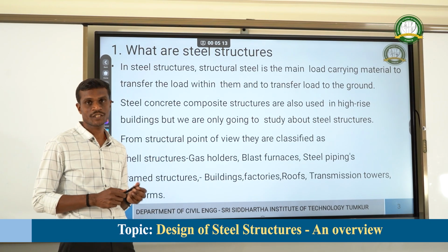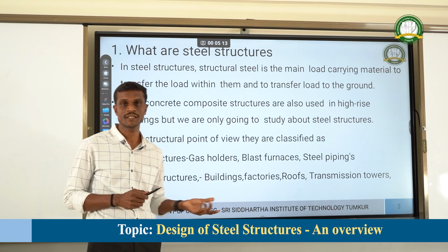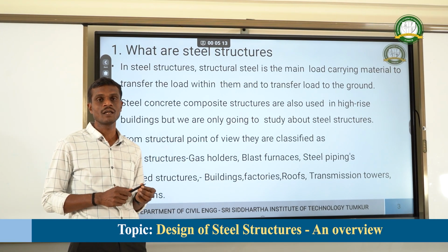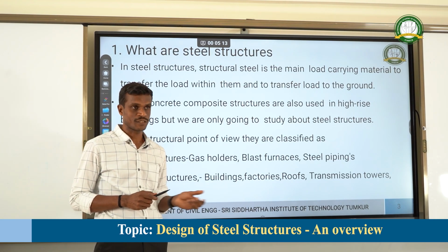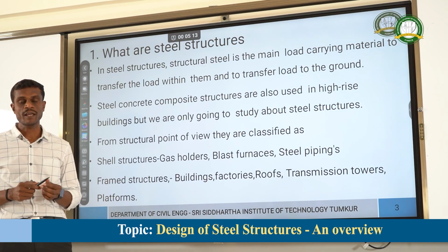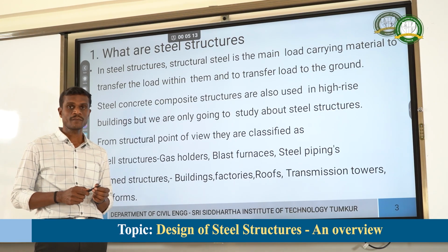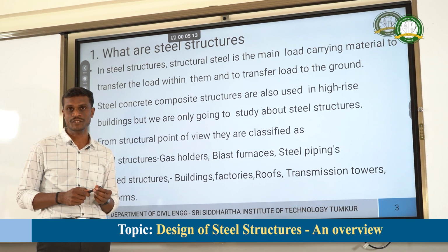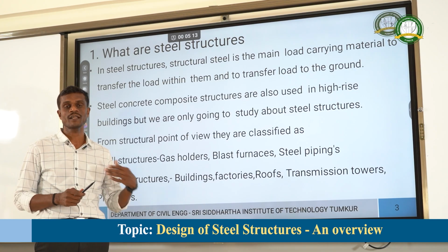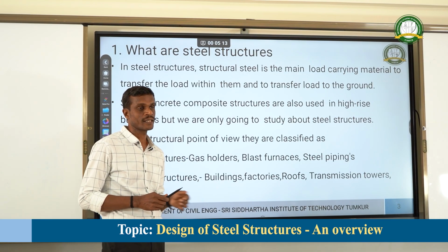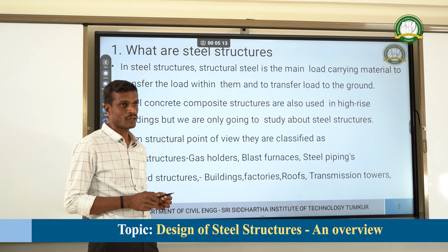So, why are we going with steel structures? They have their own advantages: construction is very easy, and if the land is not available, if the land is given on lease, at that time we have to go with the construction of steel structures. The land will be taken on lease from the customer and he will construct the structures temporarily. At that time, if they construct RCC structures, it will be a difficult task. So construction of steel structures may be useful, so that after the lease period they can demolish or dismantle the structures and shift to another place.